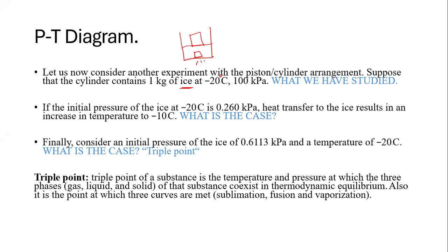But you need to understand that for water, normally the specific volume of the liquid is not greater than the specific volume of the solid. But for other substances, the specific volume is much greater. That's another point that I want you to pay attention to. Either way, when we supply heat onto our system, the temperature of the system will most definitely increase and the specific volume will increase slightly. Remember, the initial temperature is negative 20 degrees Celsius and then we heat the system. When the temperature increases, it increases maybe to about 0 degrees Celsius.